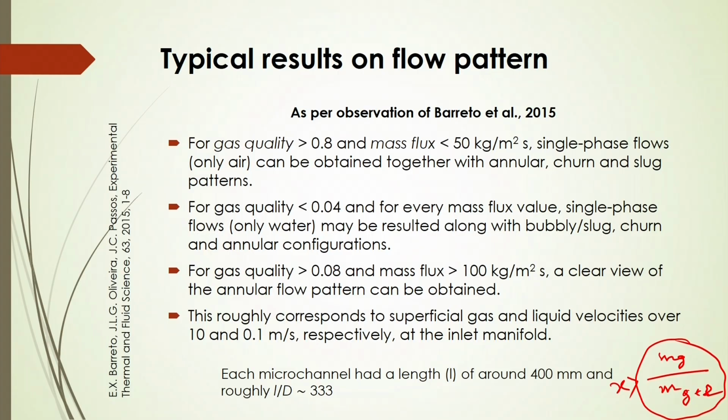For gas quality less than 0.04 and for every mass flux value, single phase flow of only water may result along with bubbly, slug, churn and annular configurations.